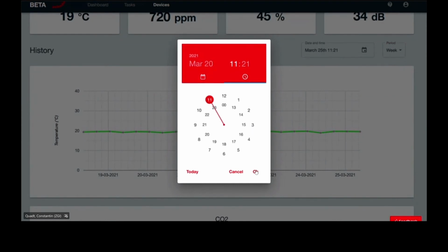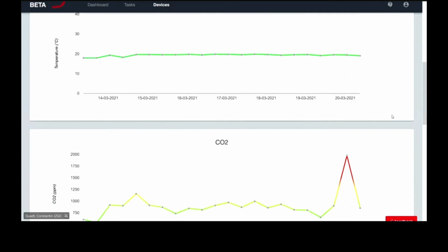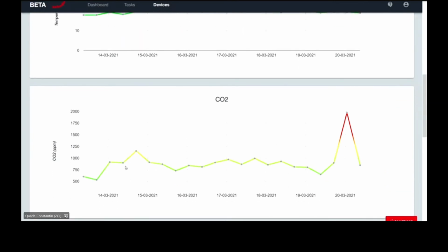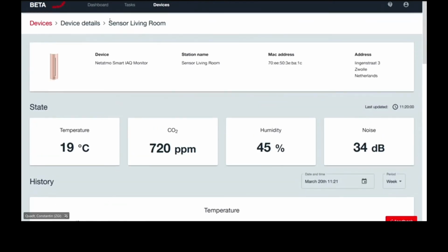We can clearly see this here in the temperature and CO2 levels that I just explained during the whole week. We can see it's in an adequate range of roughly 1000 ppm. And then here on Friday night, we have this peak that we regularly detected. With this, we can easily time-program the ComfoAir Q to regularly start at 5 o'clock every Friday night to cover the additional people gathering in the living room for the family dinner. This is a very nice advantage of the IoT climate dashboard and how even external sensors can interact with our system over an API.